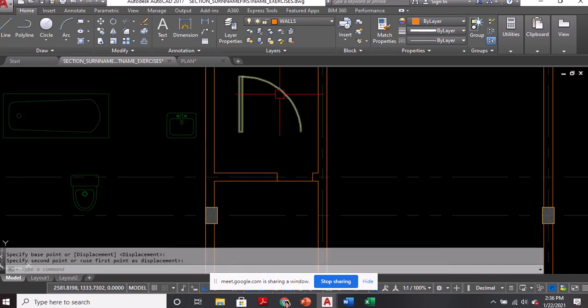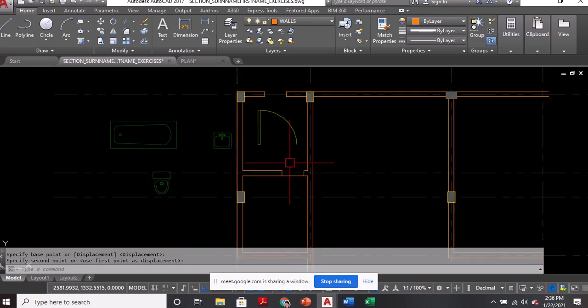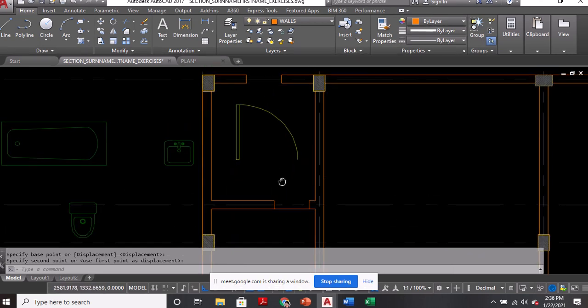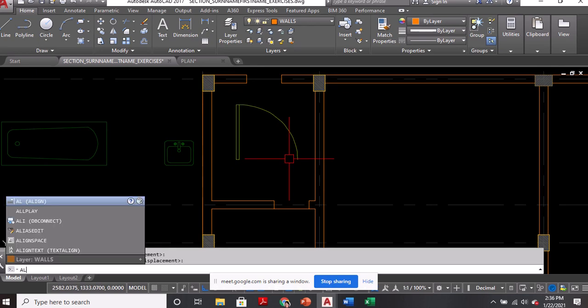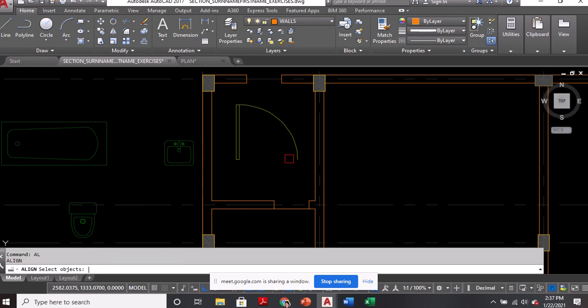Okay, this is 1 meter, if you still remember. 1 meter to. We only need 0.6 here. So, how do you do? We have one trick in CAD na isang object lang, pwede mo siyang gamitin sa iba or you're making your template flexible. Okay? So, you keep attention with this one. So, the command is AL or align. When you align an object, you move it, you rotate it, and you can also resize it or scale it. Okay? So, that's AL, enter.